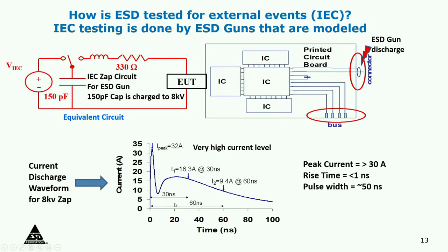So to sum it up then, all the internal pins are protected for the two models that I already talked about. All the external pins require a separate type of protection. Then you have the total protection for a system. Once a chip is inside a system, it doesn't face any more human body threats because you are now touching only the PC. You're not touching that pin anymore, but you are touching external ports of the electronic equipment.